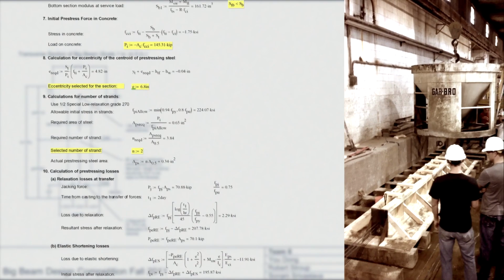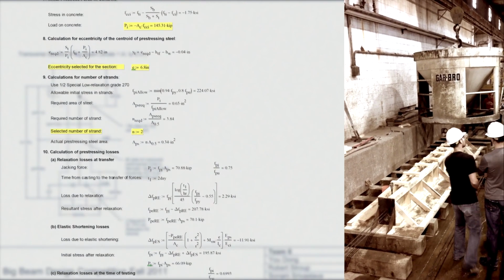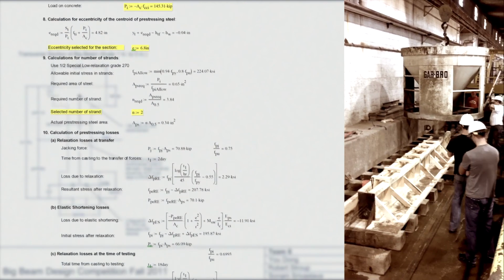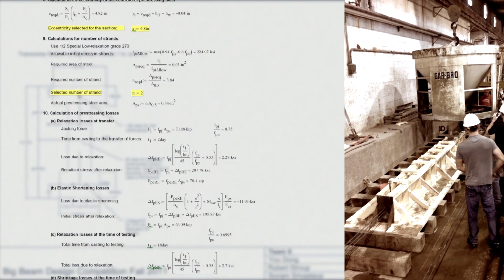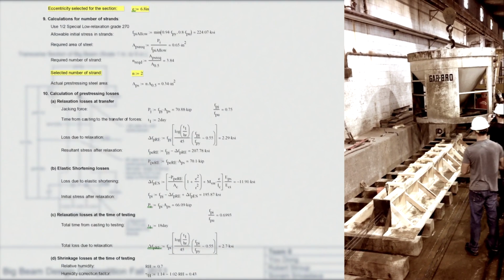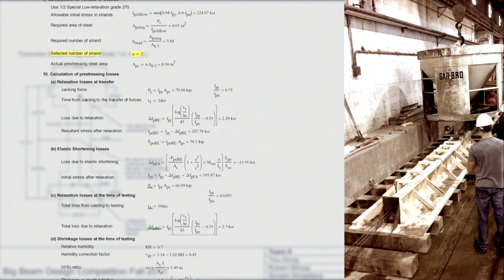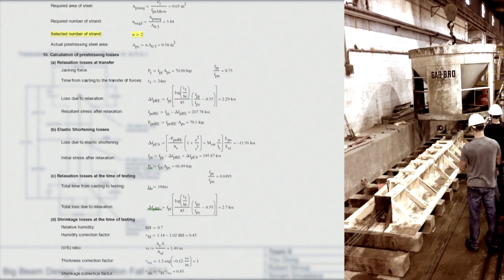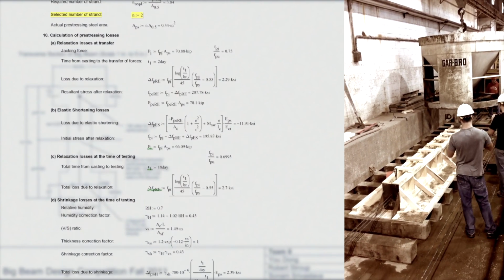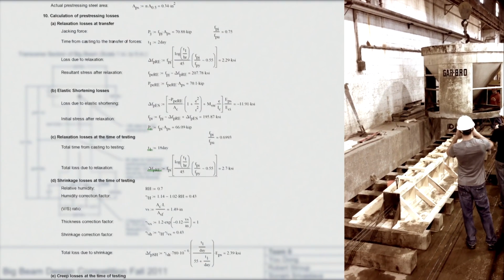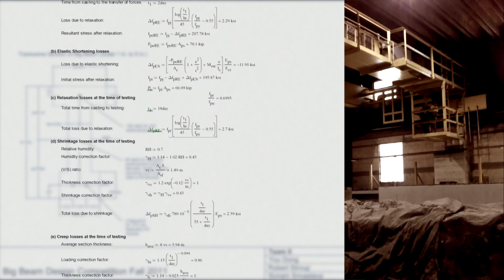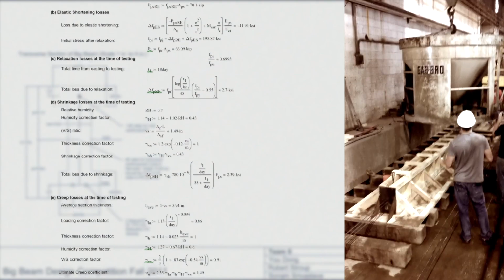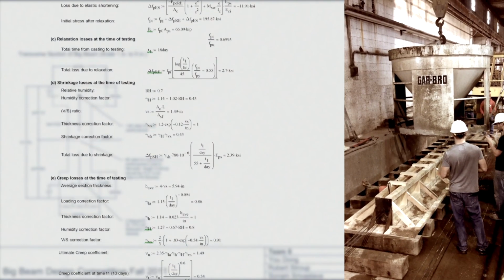In addition to the given and found values, using ACI section 18.4.2, stress limits were calculated for the tensile and compressive stresses at transfer, the compression stress at the application of the superimposed dead load, and the compression and tensile stresses at service. After the allowable limits were found for member stresses, the beam geometry was then optimized using Microsoft Excel. After analyzing 2 other geometric configurations, we chose to optimize the structural design for an asymmetric I section, with the top flange being wider than the bottom flange.